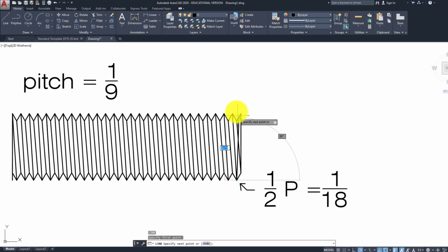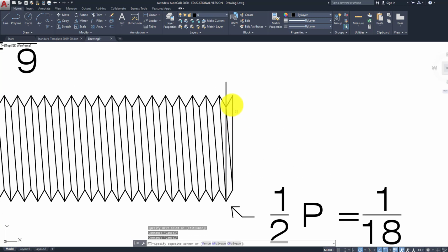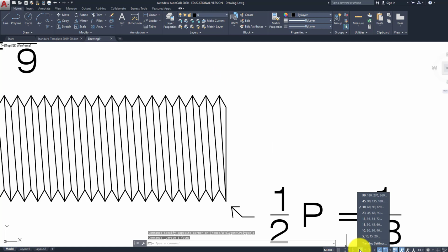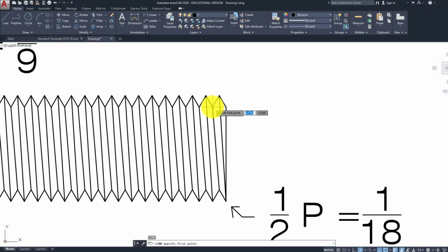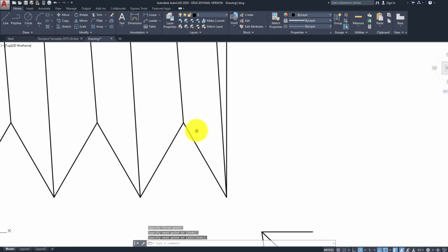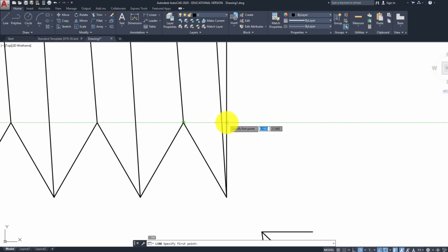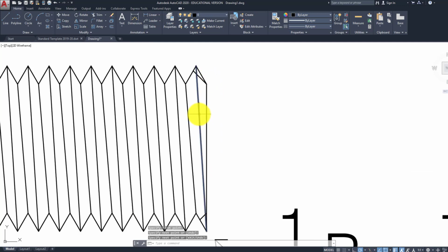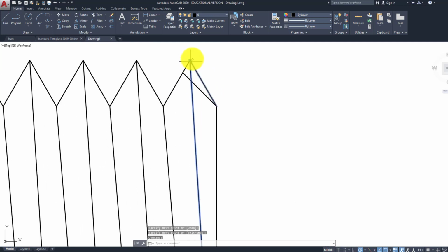So what I'm going to do is actually come up right here from this point and get rid of everything on this side. This is what I want. Basically what you're going to do is go down here to your 45, and from the minor diameter, which is this point, we got our major at the top, minor here. I'm going to go at a 45 until it hits. I'm going to do the same thing down here. So I need to go straight across and then 45 until it hits. Now if you can visualize this, this point has now been shaved off to this point.